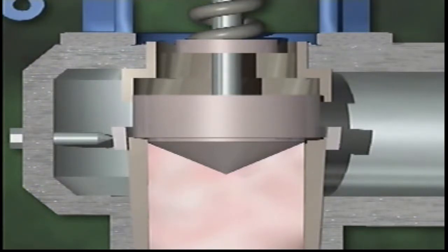This predetermined value is the valve's reseating pressure. Typically, as the force of the escaping steam is lost, the valve shuts suddenly. A small cushion of steam trapped in the huddling chamber keeps the disc and seat from slamming together hard enough to be damaged as the valve snaps shut.